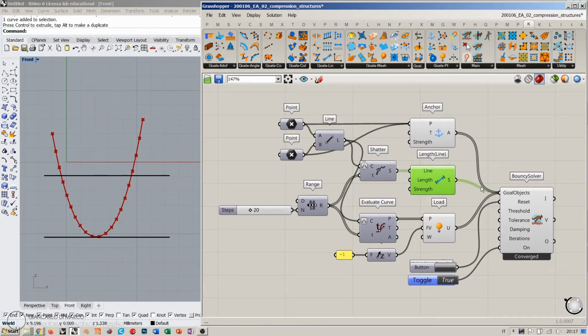Okay, so yes, it is possible to perform a realistic physical simulation with Kangaroo, taking into account real properties for materials, but the simulation becomes extremely slow. And of course, if you set the elastic strength to 200,000, for example, you also must adjust the strength of the anchor point, else the elastic property will be so strong that anchor points will start to move around.